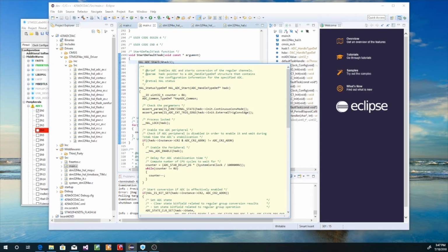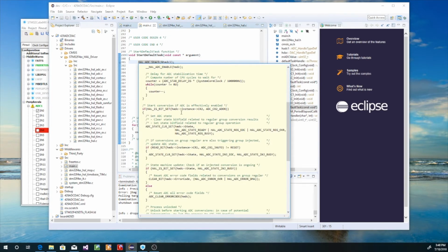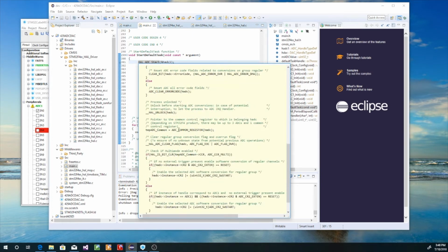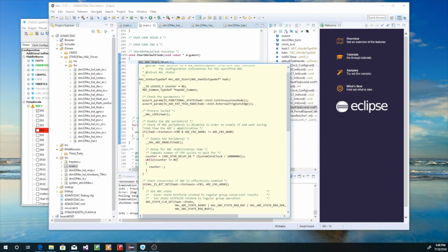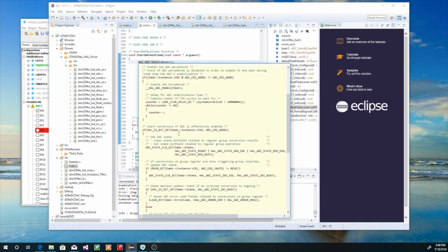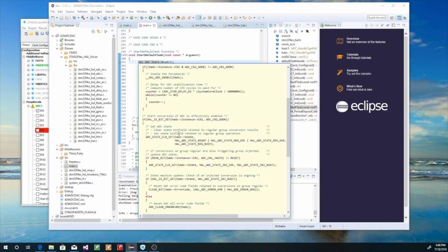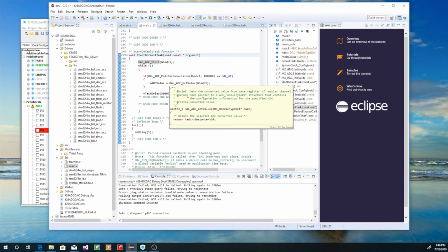As you can see, there's a large number of things that are done to start up the software. You have to keep this in mind. It's important to keep in mind all the software that's behind the scenes. The reason is, if you're making a decision about whether or not to use DMA or an interrupt, just realize that if you're using DMA, you may not get the performance out of it that you expect, because there's lots of software behind here. I'm going to show you this one right here.